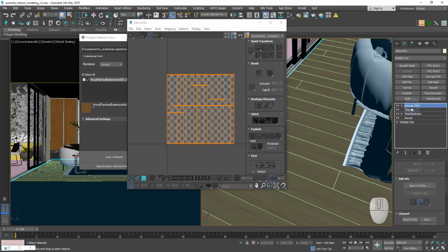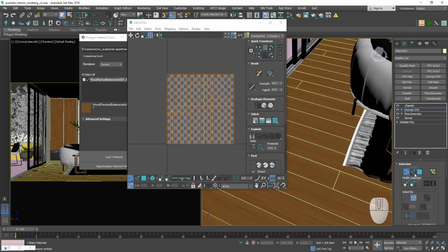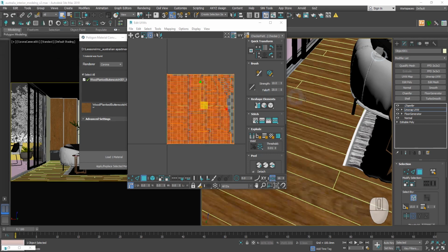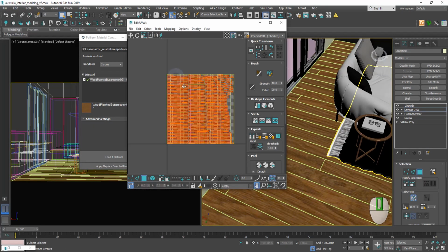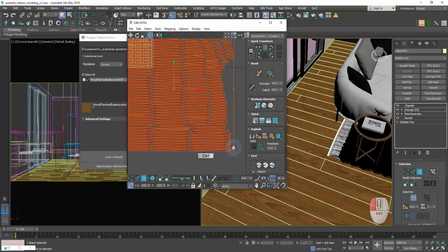Unwrapping will unwrap texture coordinates longer with Apply Chamfer. So, I suggest you put unwrap before chamfer. Select Polygons, Mapping, Flatten Mapping, uncheck Rotate Clusters box, assign a little bigger value in spacing and hit OK. Thus, each bar on the floor has its own place on the texture.